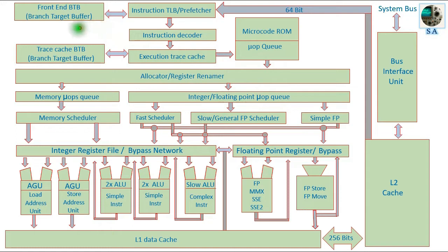Therefore, here we have accurate branch prediction logic that uses the past history of program execution to speculate where the program is going to branch to, helping prevent frequent flushing of the pipeline. Some processors use a simple static branch prediction technique, and some use dynamic branch prediction based on branch history analysis, and that is the case here.